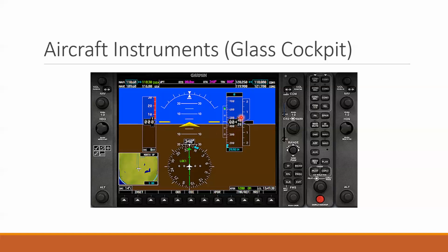And then over on this side, we have your altitude, and it has a tape here as well. And on this side, it also has a purple line. That purple line shows you basically what your altitude will be in a given amount of time. Usually I think it's like 30 seconds or something. So the next 30 seconds, it will show you where you'll be given your current vertical speed. That's kind of helpful. But it's a digital readout, so you can just read it. In this case, it would be like 430 feet or something.